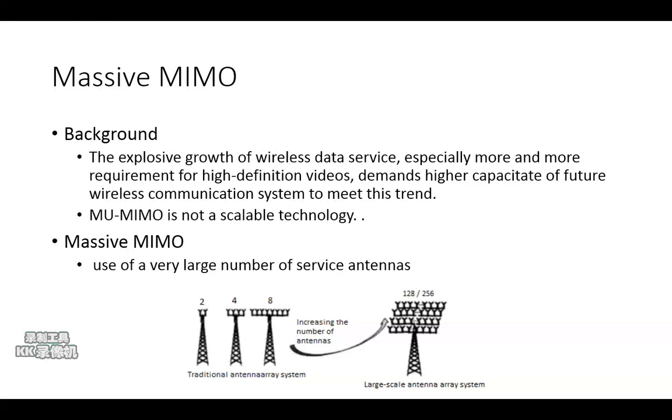Massive MIMO makes a clean break with current practice through the use of a large excess of service antennas over active terminals and time division duplex operation. Extra antennas help by focusing energy into ever smaller regions of space to bring huge improvements in throughput and radiated energy efficiency.